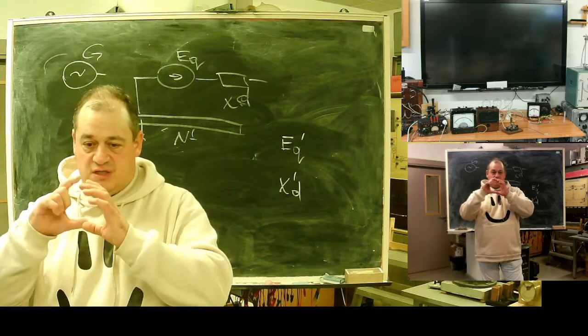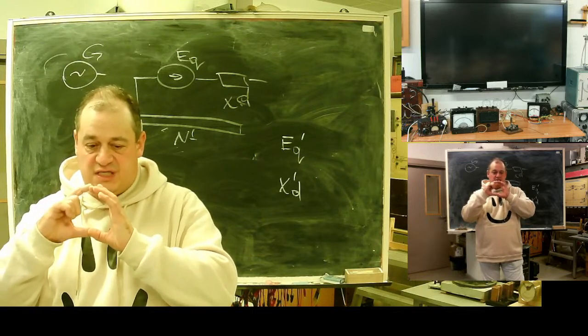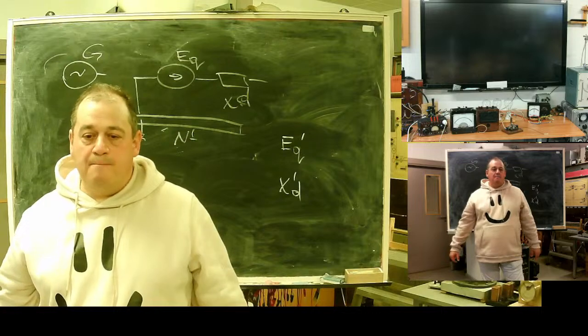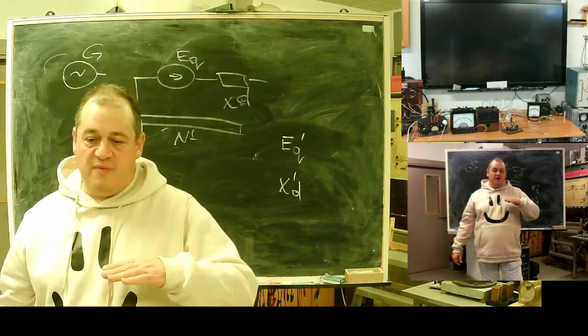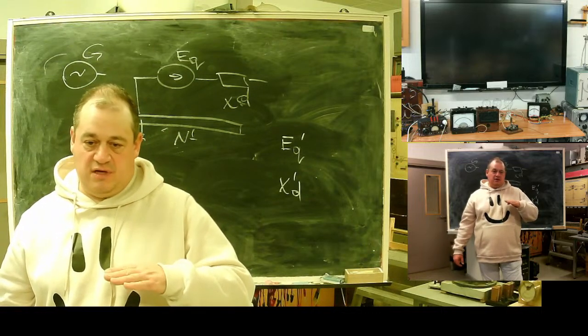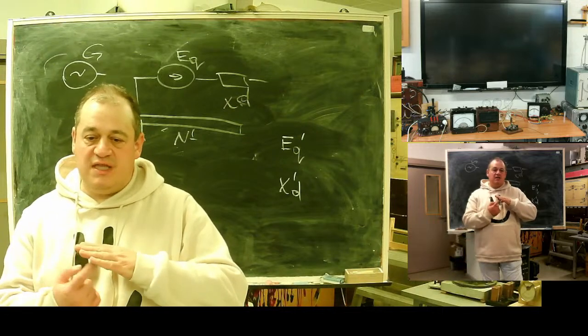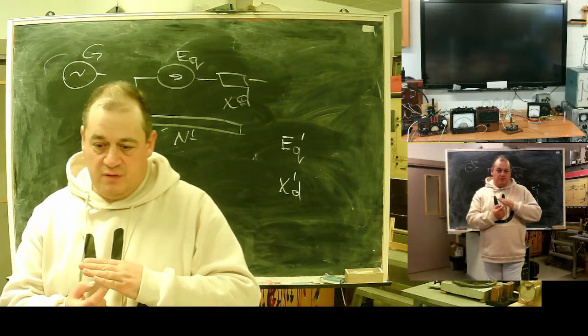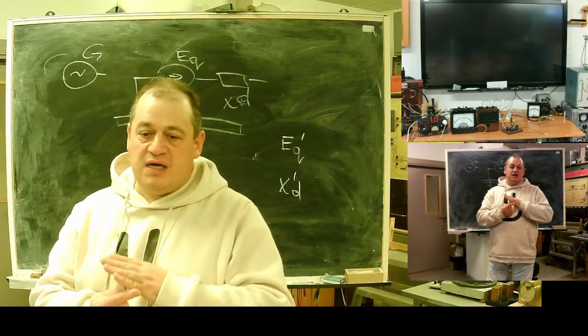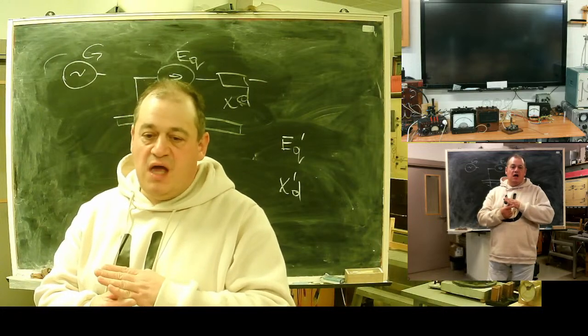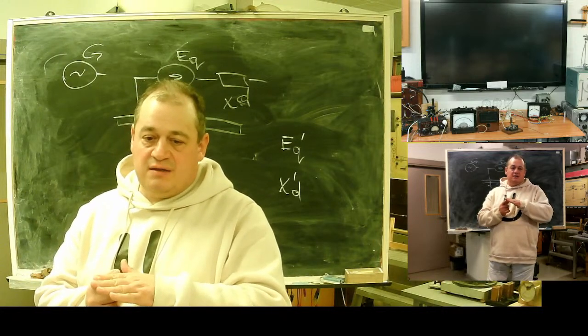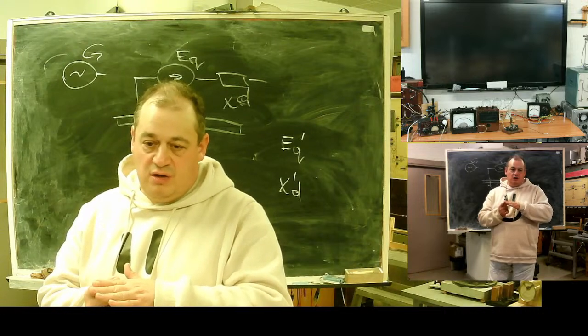Turbine wheels get holes, eaten by cavitation. Backward movement causes cavitation damage on the leading edge. It's hardly repairable, it's a bad thing. And then on the trailing edge.